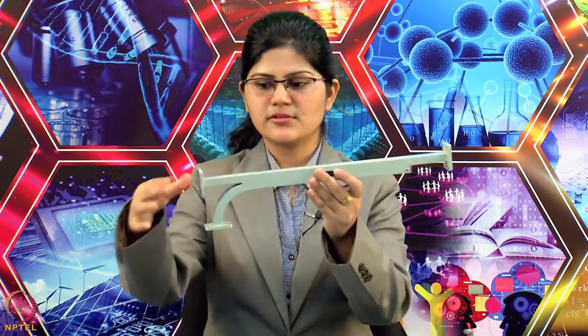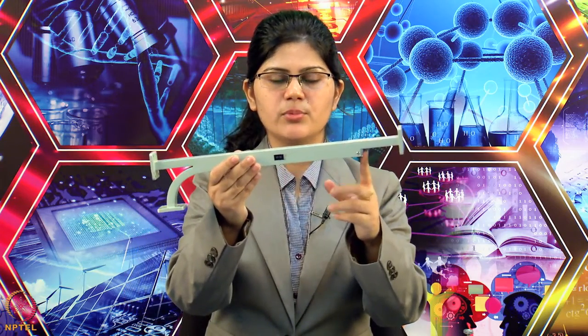Now, the next application is a coupler. In a coupler we have 4 ports: input port, through port, coupled port and isolated port. In this, this is the input port, this is the through port, this is the coupled port and this is the isolated port. This isolated port in this coupler is terminated with a matched load. This coupler is a 10 dB coupler. So, if we give input 0 dB here, then we will get minus 10 dB here at the coupled port.